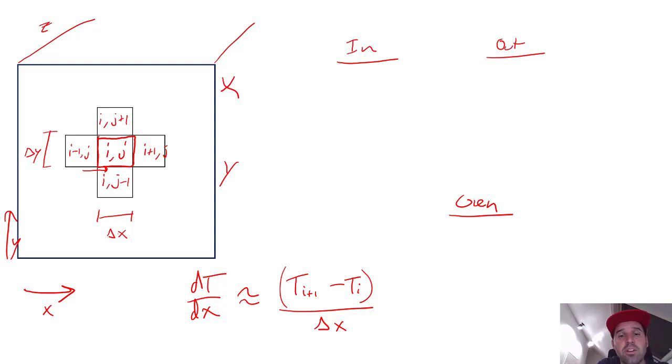That's defined by Fourier's law. So here we're going to have minus k, and this would normally be dT/dx, but we'll assume that we are dealing with a small enough system that you can approximate dT/dx as this T_{i+1} minus T_i over delta x. So we're going to plug that in here. Oops, I messed up here. For energy flowing across this boundary, we're actually going to be using i minus 1.